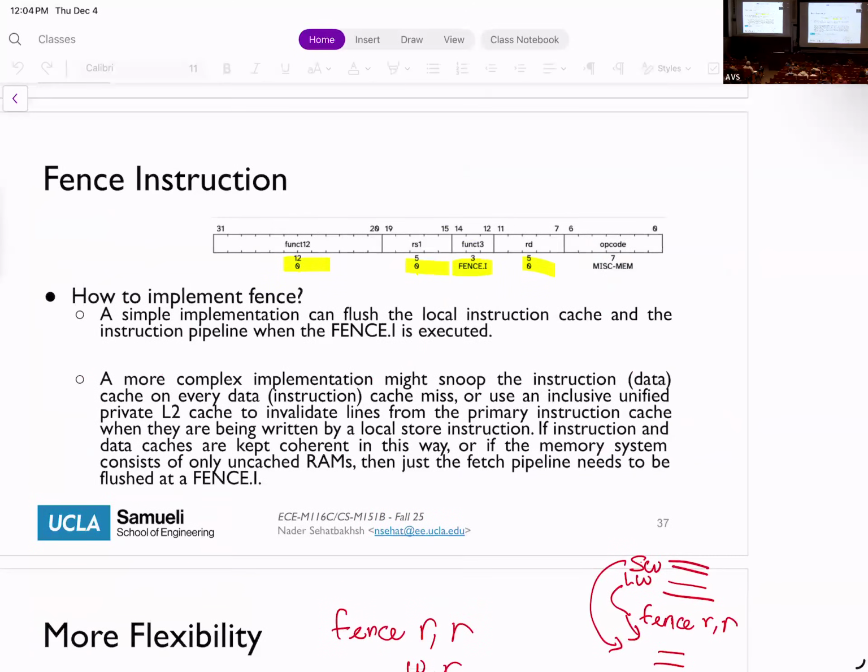So last thing we were talking about was how do we fix the synchronization issue, and how we reason about different timings, as well as how do we make sure that even if the cores and the processor are reordering instructions, we still maintain some form of correctness, some form of an ordering for the system. And that was the motivation behind these synchronization primitives that I said could be implemented both in software and in hardware. Hardware actually has a big role in synchronization primitives. We talked about two ways of synchronization, the producer-consumer and the mutual exclusiveness.